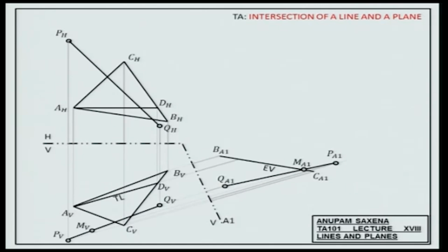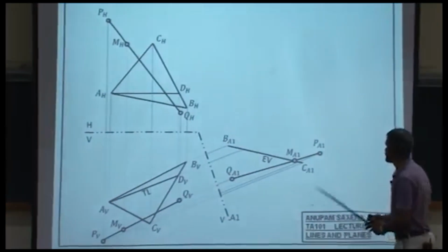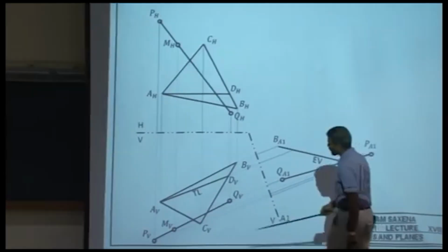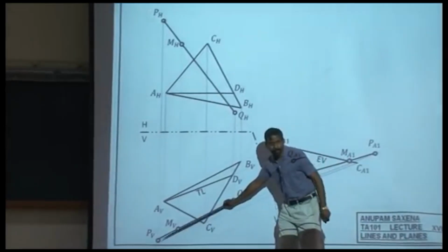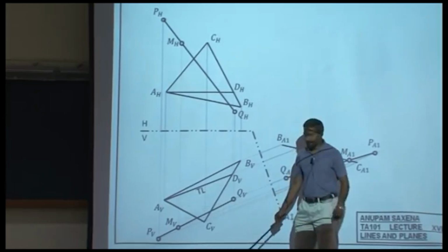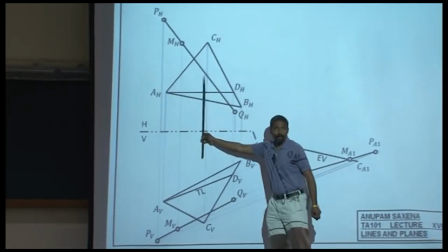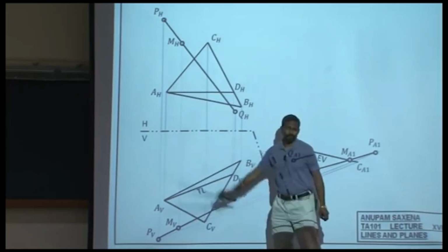Okay. So project it upwards. It has to lie on the line, alright? MH. Is it lying on the plane? Would the plane and the line intersect in this case? No? So that's the check that you would want to make. So this point has to be a part of the line and also it has to be a part of the plane. Number one. Number two, these 2 points, they should be lying on the vertical projection. Right?